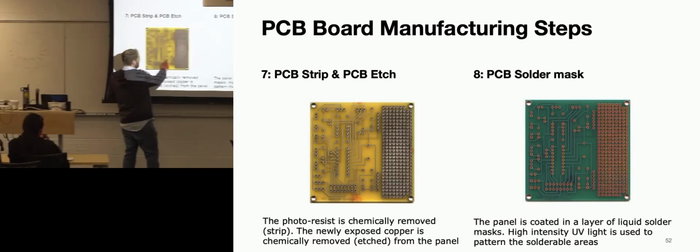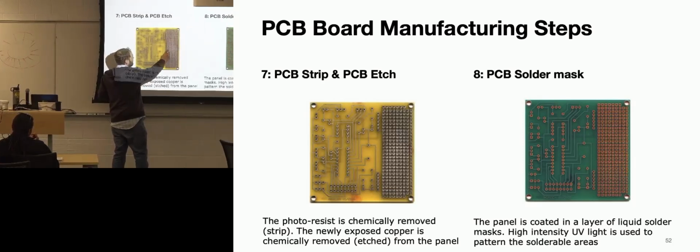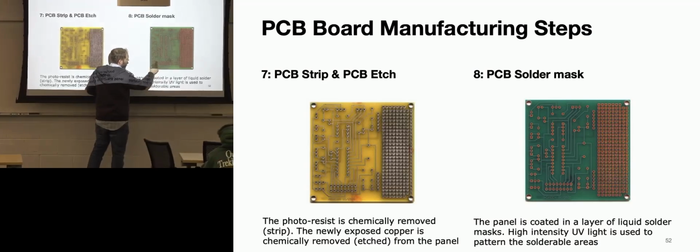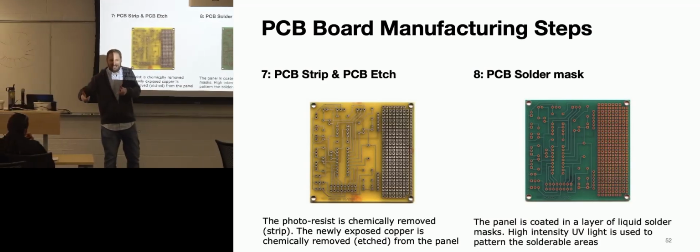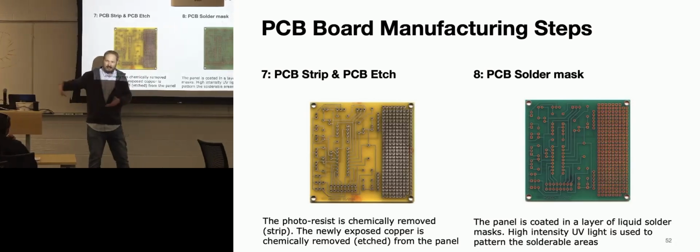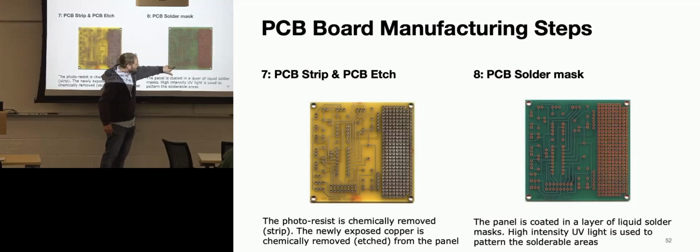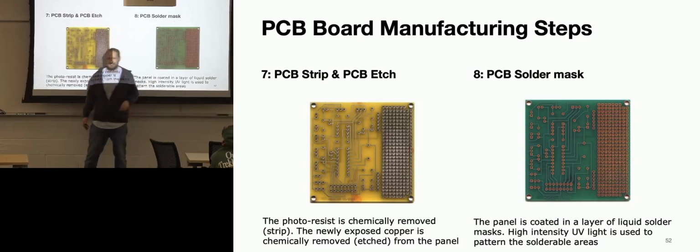So remember here, I probably can't see anything because the image quality is bad, but there are traces here and pads here, so both are exposed. By putting solder mask on, you ensure that no solder can attach here. This comes back to the idea that if you're using wave solder, with solder going everywhere, you want to protect it so it's not going to jump a bridge across here. This is not going to be covered with solder. It's generally not good to have extra stuff around, and it can cause more errors. That's why the solder mask is there, just to protect those traces.